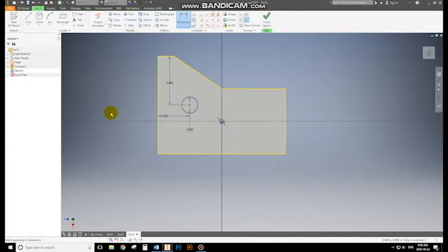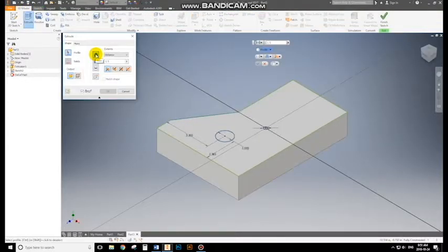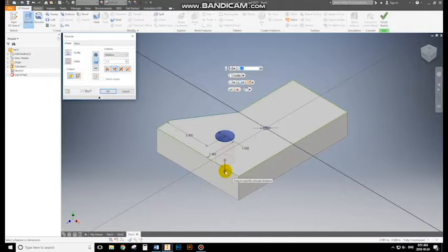In the Extrude window, we can also choose to extrude a new solid or to cut into our solid. By dragging the orange arrow or typing a dimension, we can choose to cut only part way through or to go all the way through.